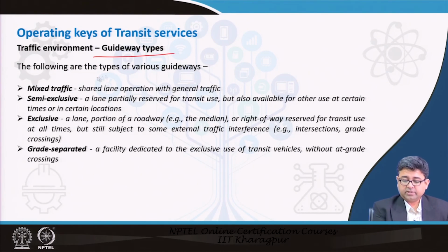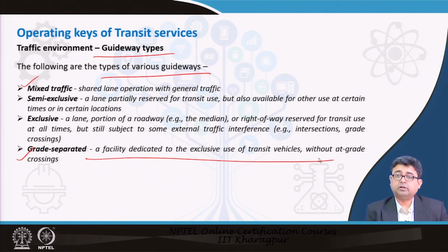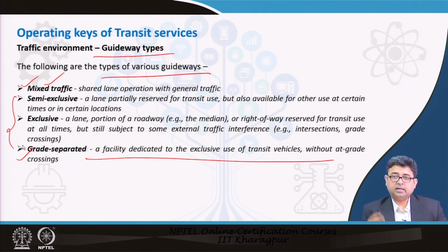Different types of guideways also have an impact on transit services. If your transit is operating under mixed traffic conditions versus grade separated conditions, the latter is very expensive to build, but it gives you reliable services and capacity that is much higher than if you are operating under mixed traffic conditions. The other two conditions are somewhere in between these two extremes.